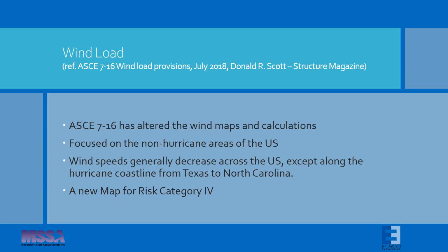The design manual does present wind speed maps, and I'll give some examples later. Those are based on actual data. It's roughly a 50-year rolling set of data that's used to calculate and update the wind speed maps. Those do change because wind speeds are getting worse, and so they periodically get updated and become more accurate. Again, that's a reflection of why you've seen some of the wind speeds go down in interior areas.